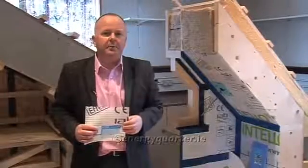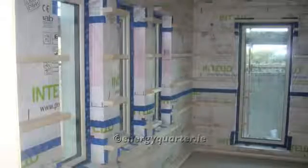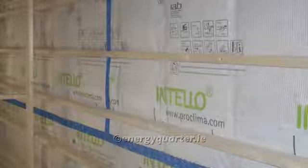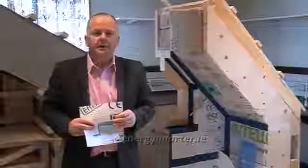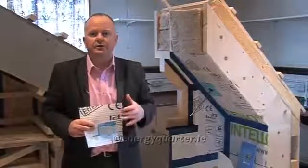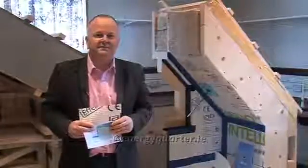But there's another very important point we have to consider in relation to timber frame construction. These airtight membranes also act as vapor barriers so that we don't have any risk of high humidity in the house migrating into the timber structure and perhaps later down the road causing problems in terms of decay and rot. So by building an airtight house, we have very high levels of comfort, and we also have a secure structural basis going on for decades and decades.